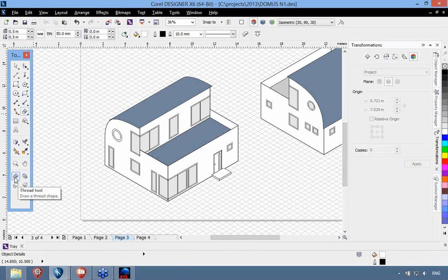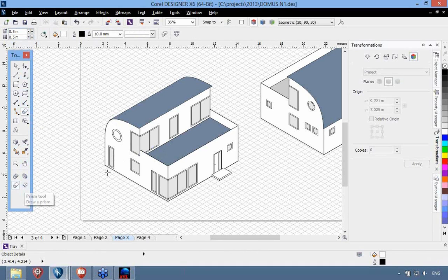So with the threads and wells, you have options for specifying radius and length, of course, the pitch, and all settings can be specified in a precise way. In this architectural sample, it's not really about threads or wells. What I want to do here is using the prism tool, and I can do that in the projection plane that I had selected.